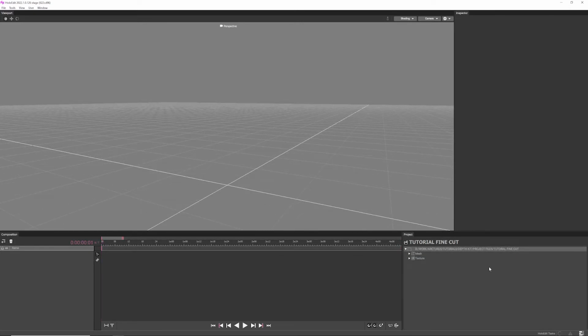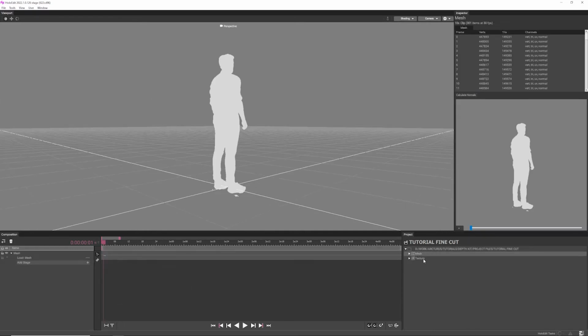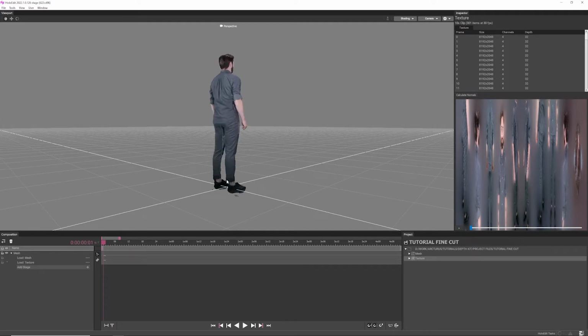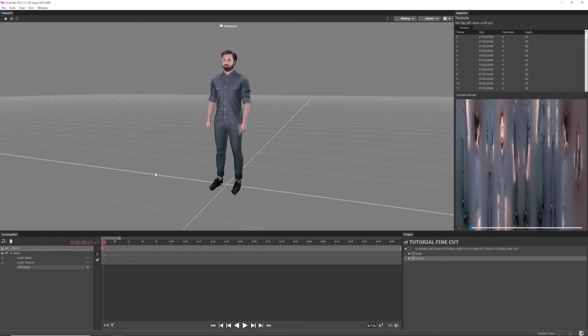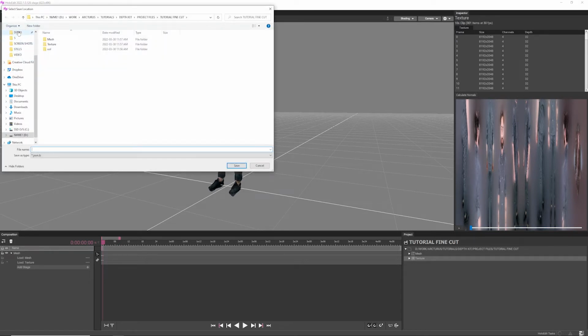With the data imported as a clip, click and drag the clip title from the project window and drop it into the composition panel. If you're seeing significant issues with the mesh upon loading into HoloEdit, we would recommend returning to the capture system export to regenerate your mesh and texture streams after recalibrating the export settings. At this point, it's a good idea to save your composition. We would also recommend creating a save file after each stage of finished processing. Let's call this one load_asset_demo.